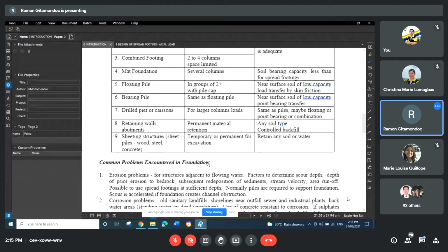So it can prevent lateral displacement of the surrounding soil as you excavate the soil within the project. You have to provide retaining structures. Commonly used are the steel sheet piles, which are driven side by side in order to retain soil material. Sometimes these sheet structures are also used to retain water, in case the water table is intercepted by the excavation, so we don't want water inside our excavation area,